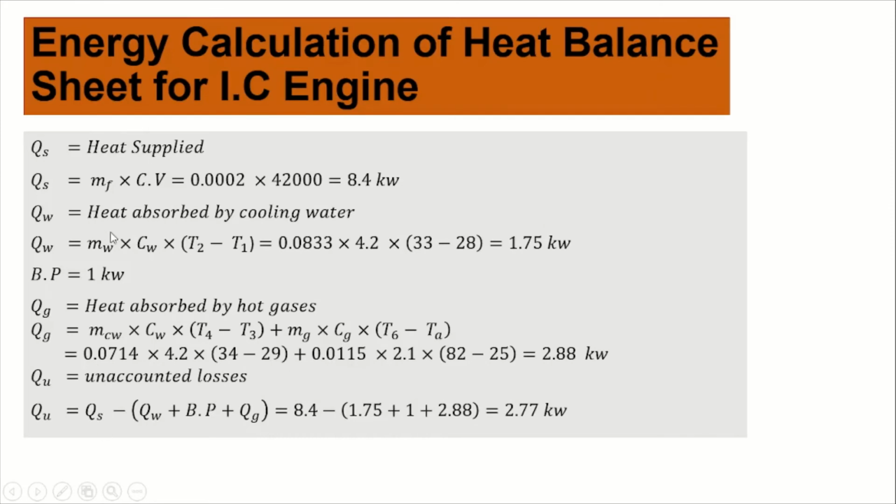Here, for the heat balance sheet, we require the energy calculation. First, our inlet energy is the heat supply. Its formula is Mf multiplied by the calorific value. So we get the heat supply as 8.4 kilowatt.